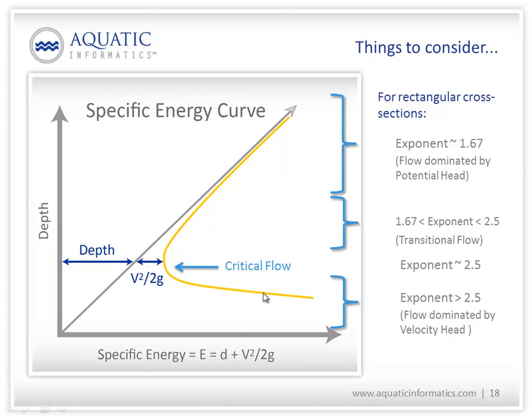But you get into this supercritical flow where it's really the velocity head that's controlling things, and then your stage, your change in depth, doesn't really tell you a lot, doesn't give you a lot of resolution of the discharge in the stream, because the energy changes so much over just a very narrow range of discharge.